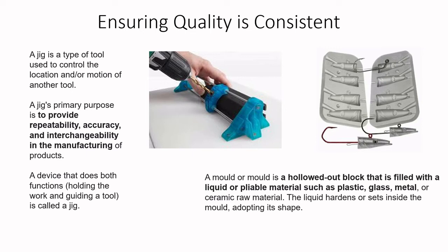There are instances in exam questions where it's about making a bike frame and obviously parts of it have to be welded. So how do you make sure it's welded accurately each time? Well, someone can put all the parts in a jig, which holds it in place perfectly, and then someone just comes along and welds it in 3 or 4 places, and it's done. So it's basically helping you hold it in place, and show you where you need to go.